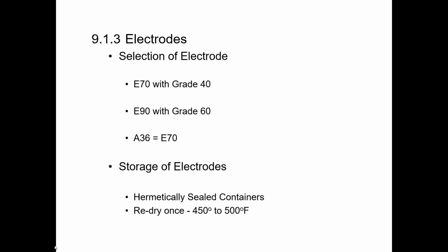or E70 in this example. So mark out E90 and write E70. So the reason that we're making these changes is because in precast plants, it's very, very rare that you would be making what's called a butt weld.